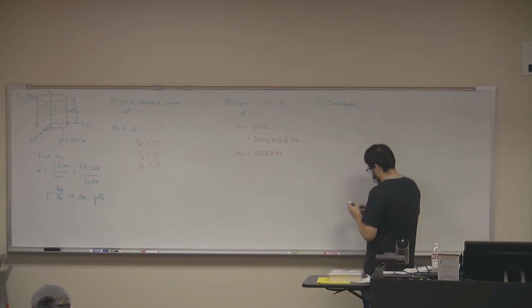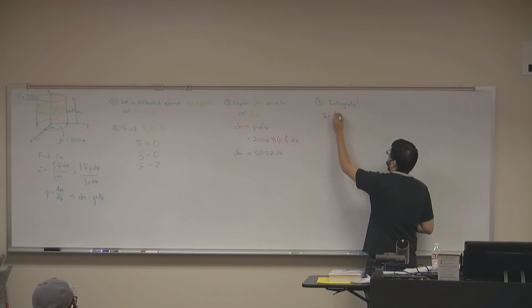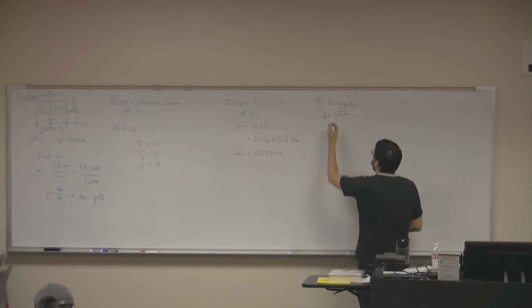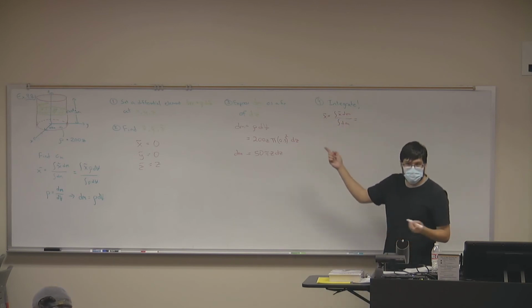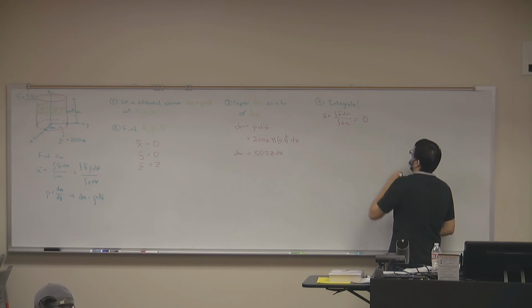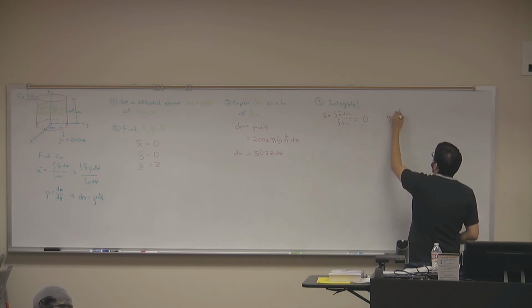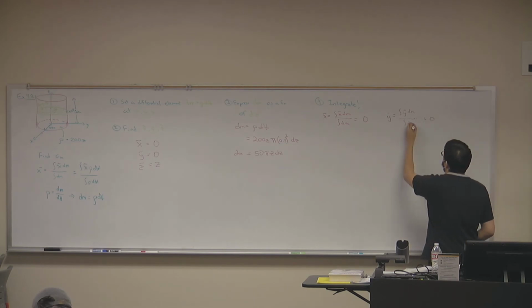We know that my x coordinate of the centroid, x bar, is equal to the integral of x squiggly dm. I said centroid, I meant center of mass, over dm. x squiggly equals 0. Thank you, Jenny. So x bar equals 0. We can say the same thing for the y coordinate. Y coordinate equals integral y squiggly dm over integral dm, but y squiggly equals 0. Therefore, this coordinate equals 0. So that doesn't change. Those are the values we were expecting.